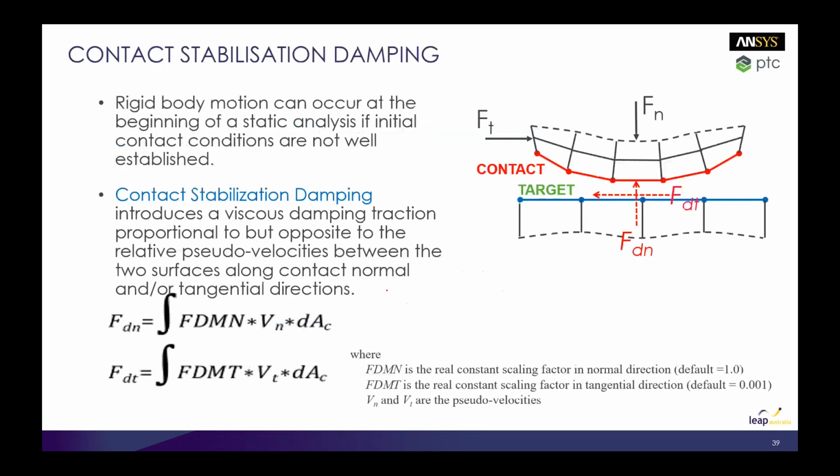Okay, so what we can introduce is what's called contact stabilization damping. This introduces a force that's proportional to what we call the pseudo velocity. With this force, this body will move a certain amount in a time step. But at the same time, we've got essentially a damper here.